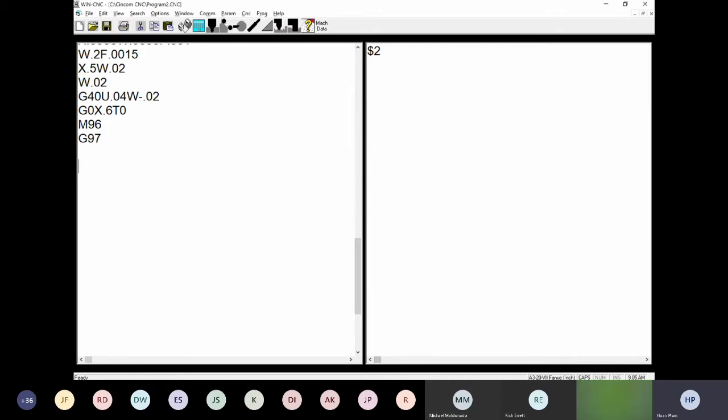Next thing we're going to do is the milling. For milling, we already agreed we're going to use tool number 7, and then again, no offset calling right here. So we're going to say milling 2 flats. All right, and then give the operator some information right here. Quarter inch square end mill.